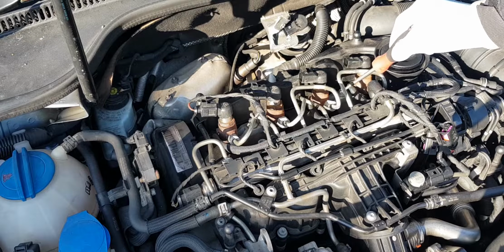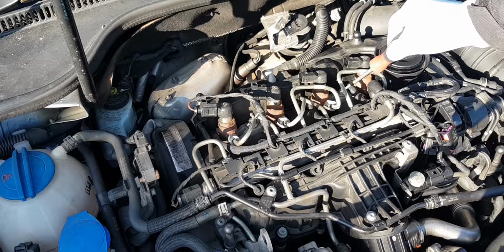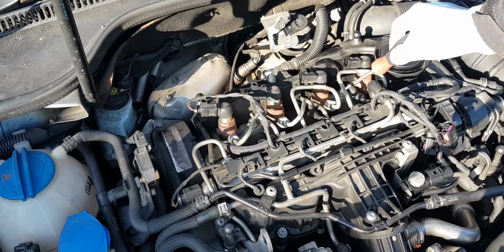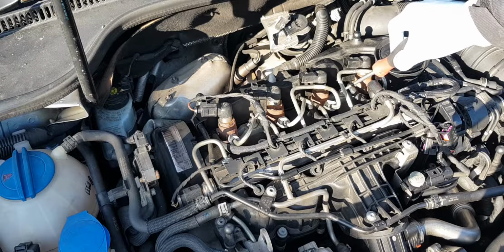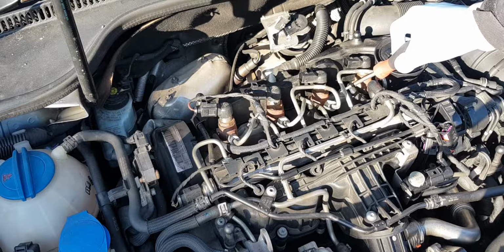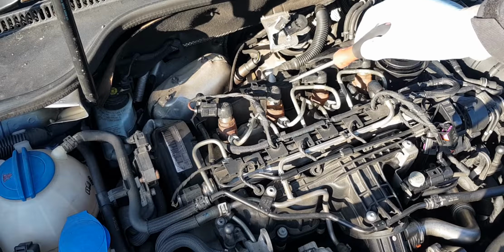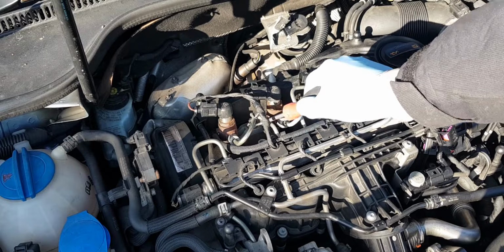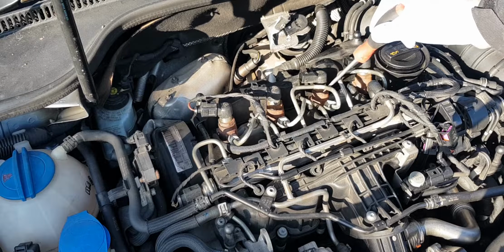So you have one Torx bolt, which is a stretch bolt. VW recommends to replace it. They're not expensive. I'm in the UK. I paid about £1.30 plus VAT, so about, I think it was just over £1.50 for one of the bolts. I have got another one spare in case I need to do the other side at some point, but for now I'm gonna be replacing number 3 injector.